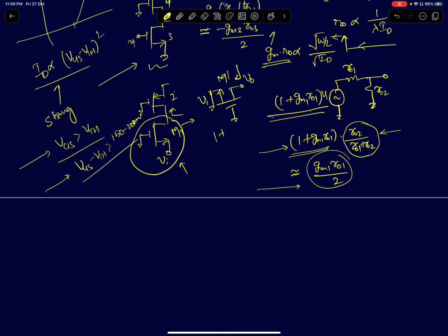Then why do we teach you all the square law characteristics? The reason is that the square law characteristics help you in forming certain intuitive understanding of MOS circuits. We get a feel for what is happening in the MOS circuit. Otherwise, if you just sweep your dimensions and currents to find the right gain, it will not look intuitive.